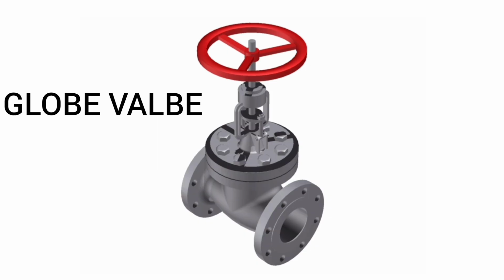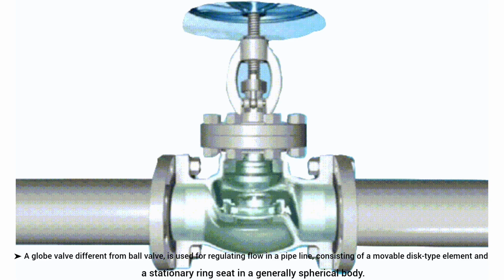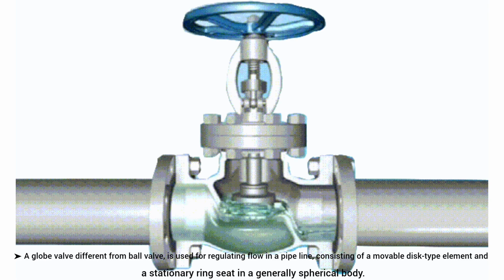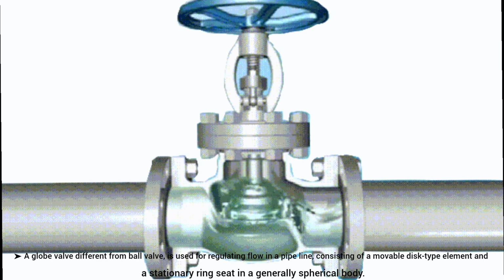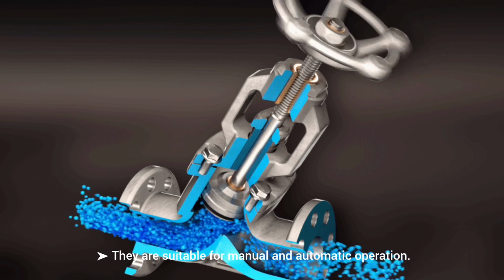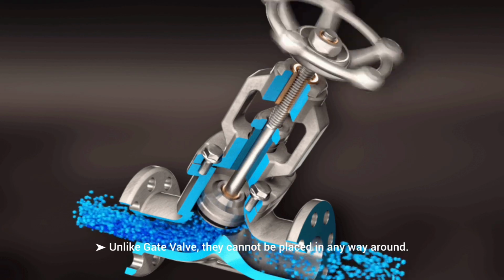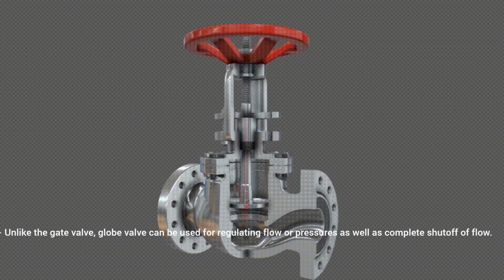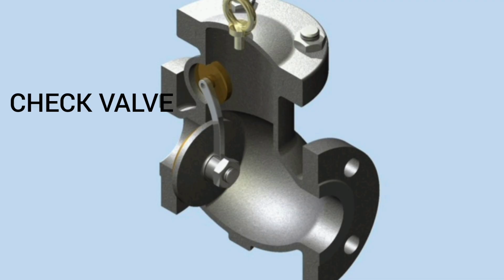Next, globe valve. A globe valve, different from ball valve, is used for regulating flow in a pipeline, consisting of a movable disc-type element and a stationary ring seat in a generally spherical body. They are suitable for manual and automatic operation. Unlike gate valve, they cannot be placed in any way around. Unlike the gate valve, globe valve can be used for regulating flow or pressures, as well as complete shut-off of flow.